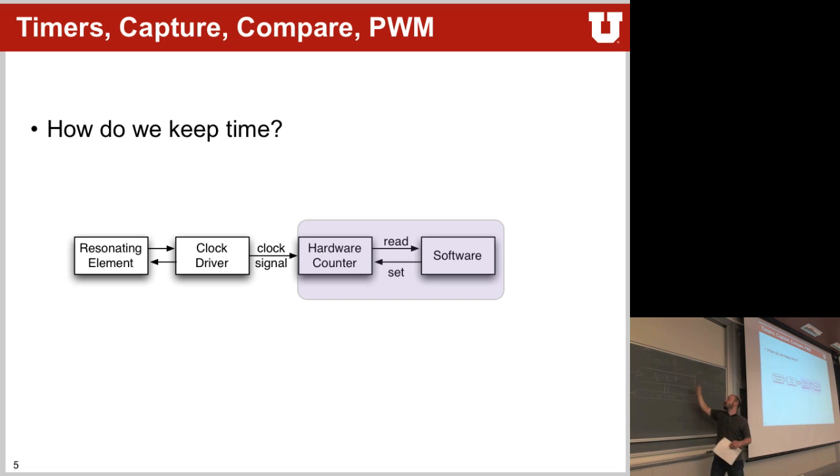Right. Incrementing doesn't mean that what is on here is just one too low or one too high, because the increment is actually flipping a lot of different bits occasionally for incrementing just by one. So if you capture it in that instability, you will actually capture garbage in here. That will just be this value at that instant in time where this was still flipping around. You're saying the capture will capture...